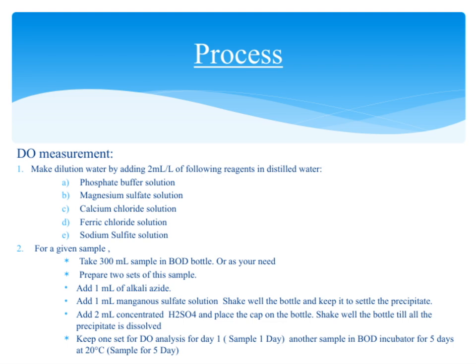One set will be analyzed right away on day 1. This is our initial sample. The other set goes into a BOD incubator at 20 degrees C for 5 days, where it will undergo biological oxygen demand testing. This process ensures we accurately measure the oxygen consumption over time, which is central to understanding water quality. Remember, precise preparation and timing are key to reliable results.